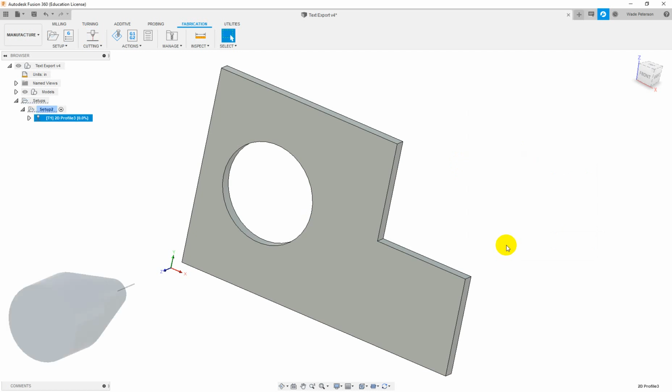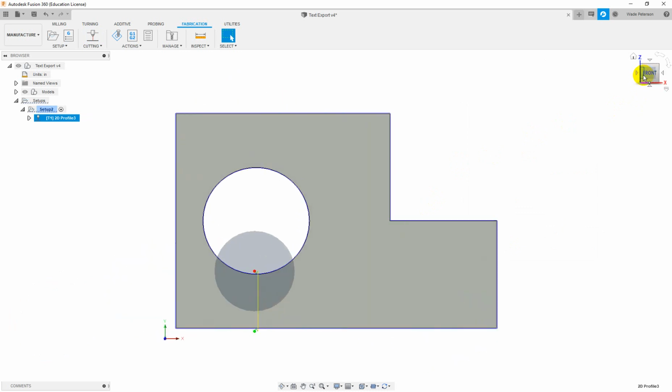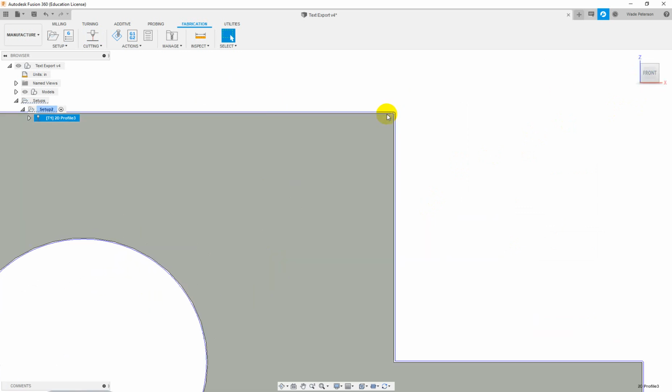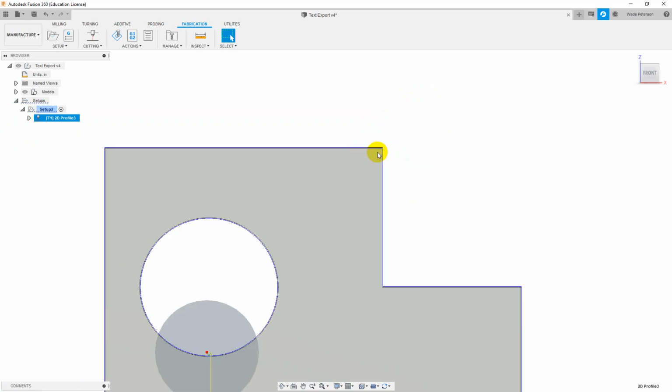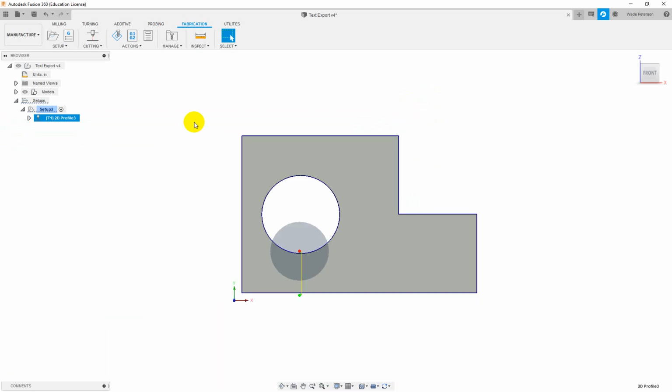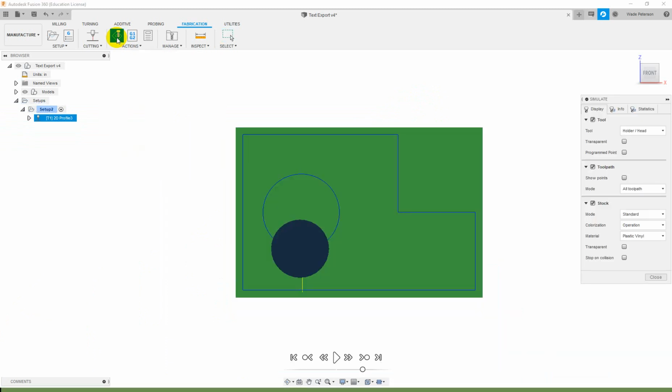We've got all our settings set, and it should go and apply toolpath. And if we go to a straight on view, you can see you have this blue line on the outside that shows you that you've offset a tool radius, and in this case it's 5 thousandths. Then what we want to do is we want to simulate and verify the tool, mostly for one, to see that it worked, and two, to see that it's cut in the right order.